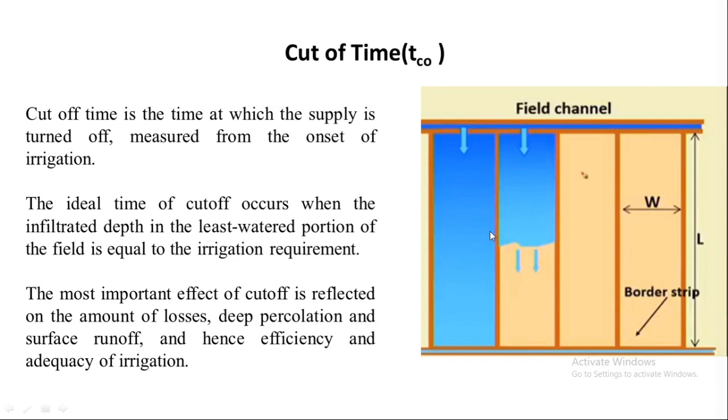If the cutoff time is too late, it might result in runoff losses and deep percolation losses, and if the cutoff time is too early, it will result in an inadequate amount of irrigation.